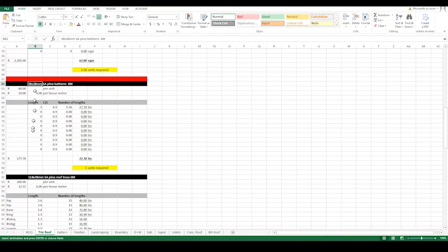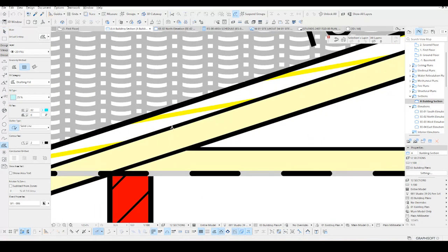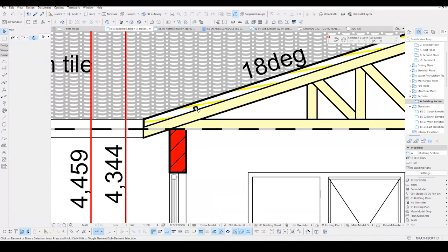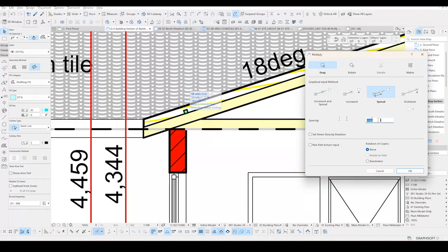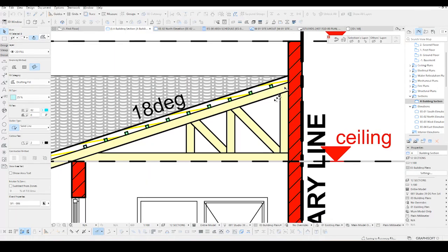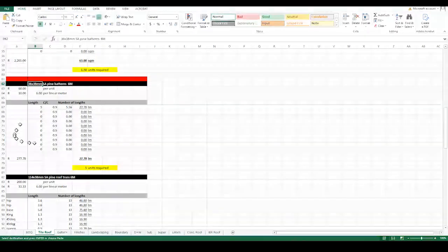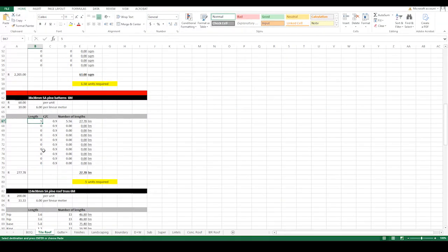And then the amount of purlins. Now the purlins are the 38 by 38 millimeter battens. So 38 and then 38. That's where they sit. And then they sit at 300 center to center, so they would sit like this. Look at me now, I'm explaining construction, but nevertheless what I need is the same formula that I was just showing you guys.